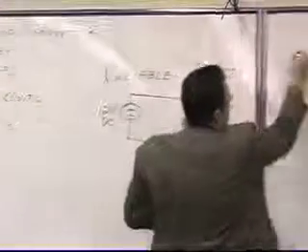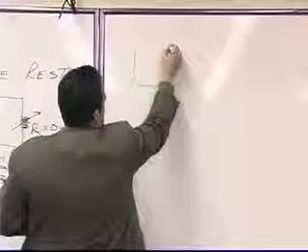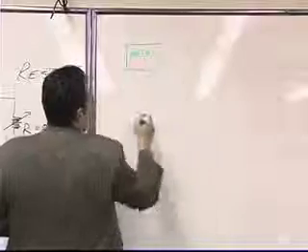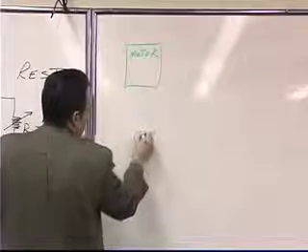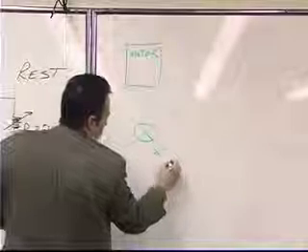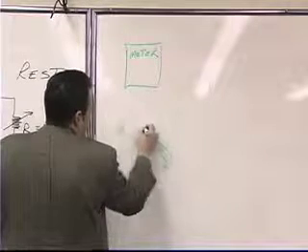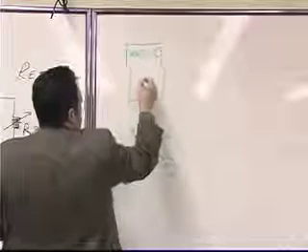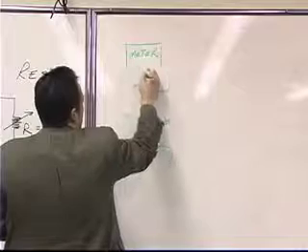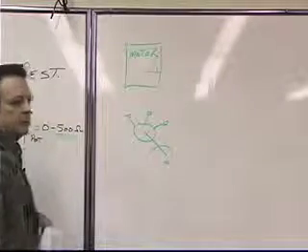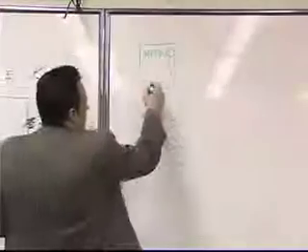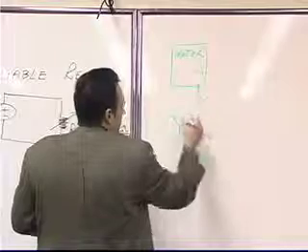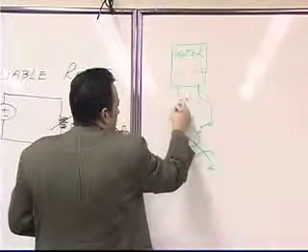In other words, if this is your meter, and this is your potentiometer, and you turn it clockwise, and you have 3 leads, and you set your meter to measure ohms. So your meter is measuring ohms, and then you take one lead from your meter and you connect it here, and you take the other lead from your meter and you connect it here,